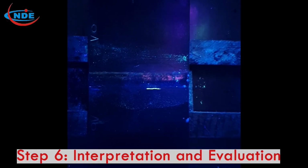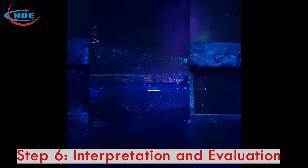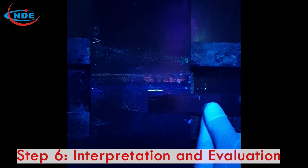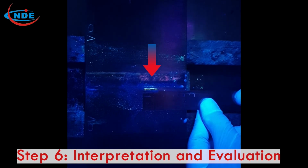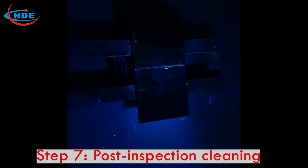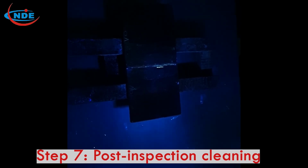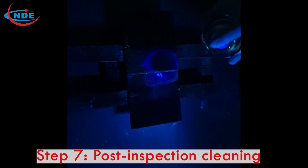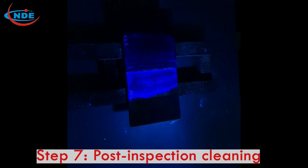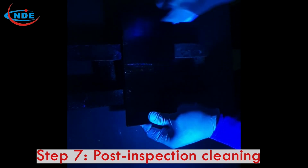Step 6. Interpretation and evaluation. Measure the size of the continuous indication and evaluate according to the applicable standard. Step 7. Post-examination cleaning. Using a solvent spray bottle and clean rag to remove used material on the surface of the testing object. Ensure that the penetrant material doesn't damage the object.